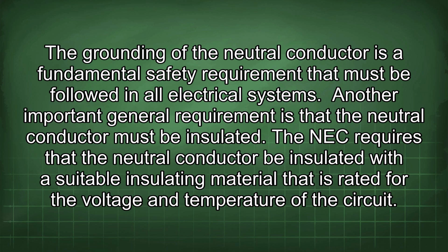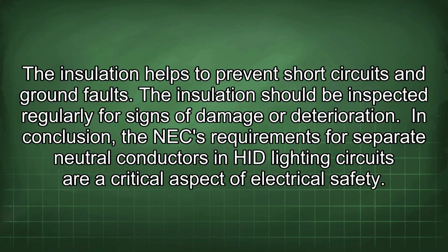Another important general requirement is that the neutral conductor must be insulated. The NEC requires that the neutral conductor be insulated with a suitable insulating material that is rated for the voltage and temperature of the circuit. The insulation helps to prevent short circuits and ground faults. The insulation should be inspected regularly for signs of damage or deterioration.